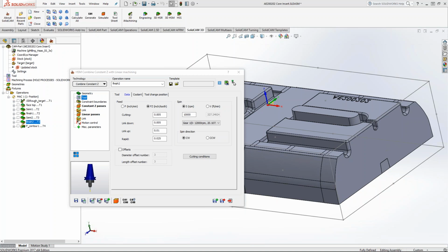So if you were to do a 3D machine on a 50 Rockwell, would you change your scallop or your wall offset to, you were saying about 8 to 10 thou? Yeah, if I had the harder material, I would leave less stock on for finishing. Okay, which makes sense.